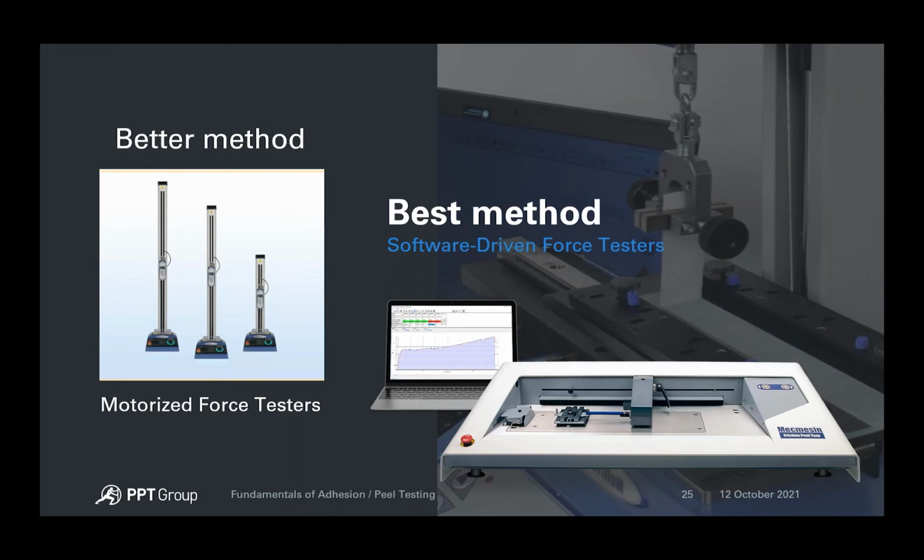For example, let's say you want to peel a tape specimen at the rate of 300 millimeters per minute for a distance of 40 millimeters. Now, this is a repeatable and accurate process as far as the how far and how fast, doing it the exact same way, as both are critical to generating repeatable results. With this setup, you'll run a test the exact same way regardless of the operator. And of course, the gauge will accurately measure the tensile force that was applied.